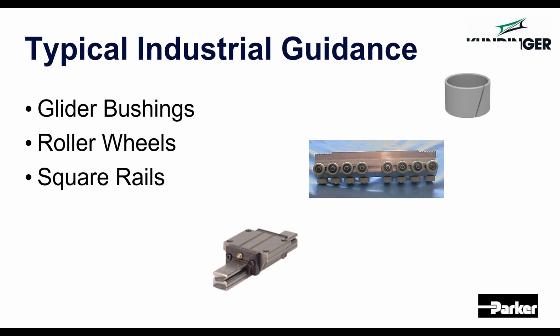So disadvantage here though is there is no inherent mechanical advantage for the motor. So you will end up in a high load, high speed type situation. You may end up having to add a gearbox between your motor and your actuator to make this work.